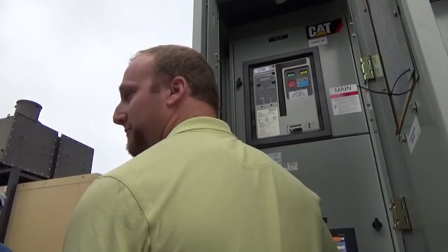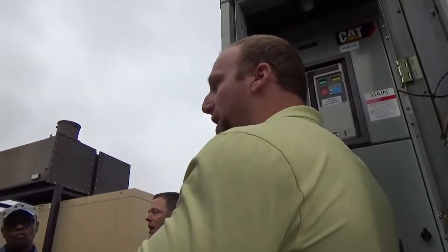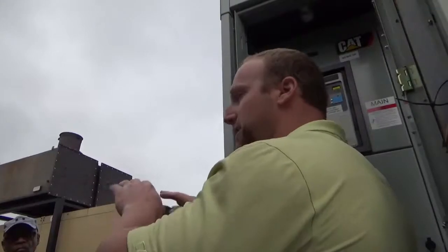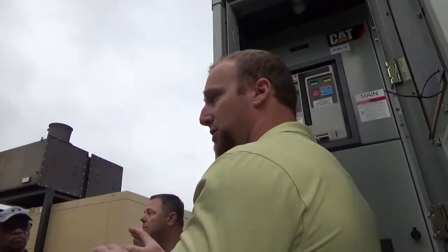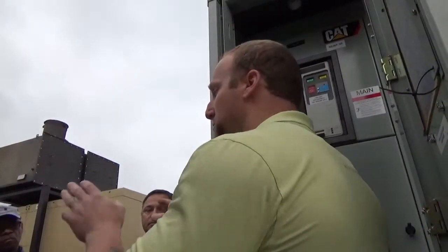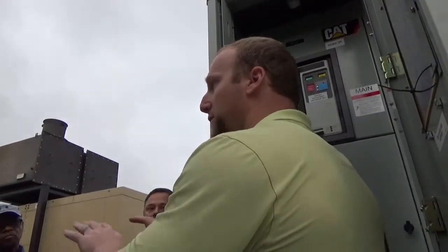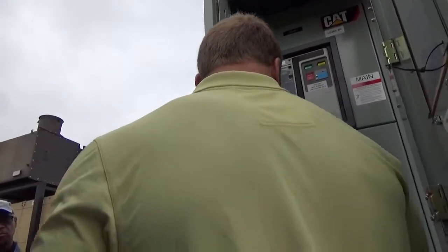So right now we said both come up and go to idle. So in an outage situation, both gens come up. The first one to rated speed and voltage closest to the bus, the second one will parallel to it. So then they both are parallel. They're both running for a set duration, which, let's go ahead and look right now. Load sensing, load stabilization delay is 1 minute. Remove delay 1 minute, so 2 minutes.